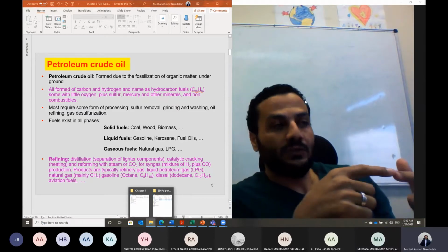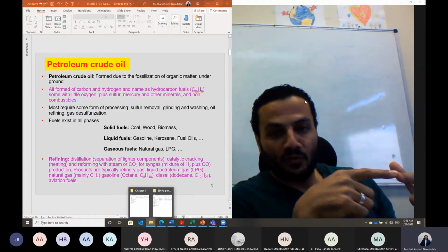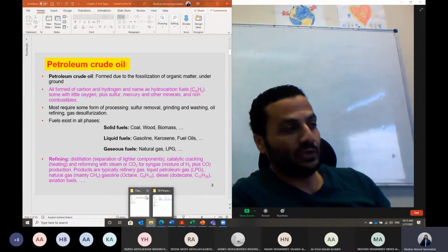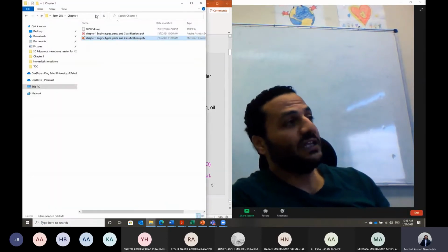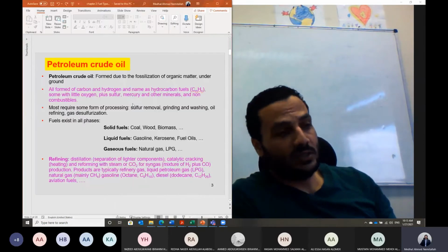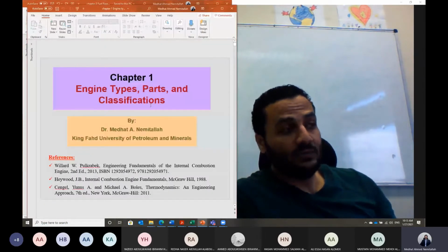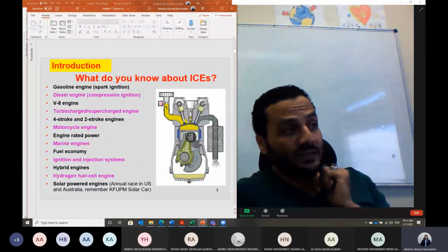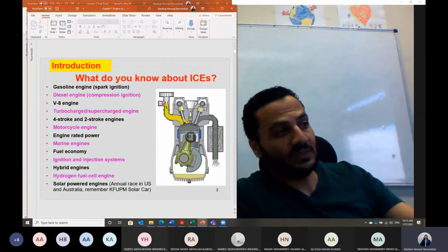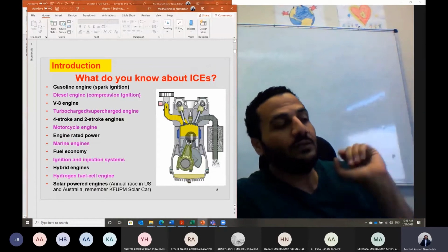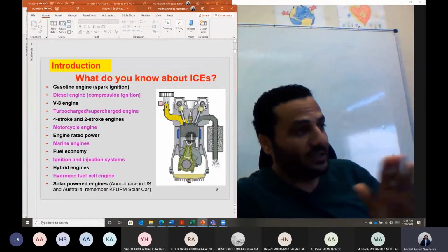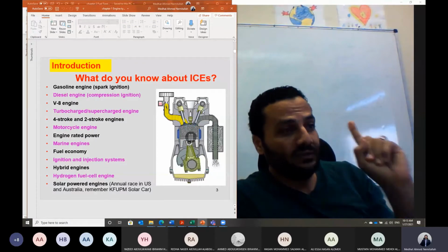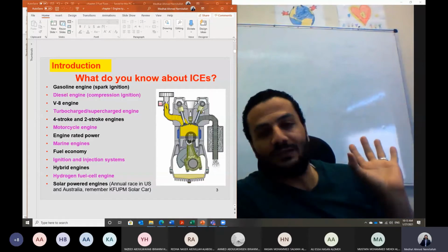If you look at the design of the internal combustion engine, the intake and exhaust valves are opened using a camshaft. And from the cam design, we cannot change the timing of the valve. It cannot be advanced, it cannot be retarded. Here we have the cam. Once the tip of the cam comes and presses, it will open and it will close. That will not change at any speed. The camshaft just opens the valve one time, the same distance for each cycle.